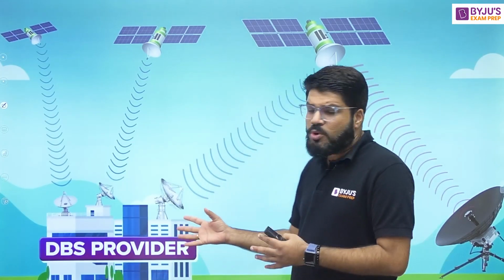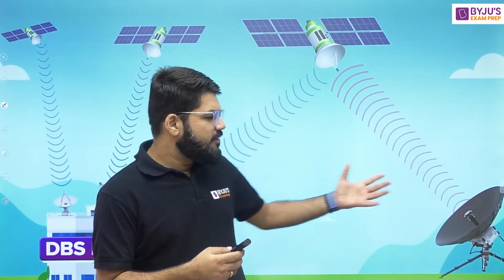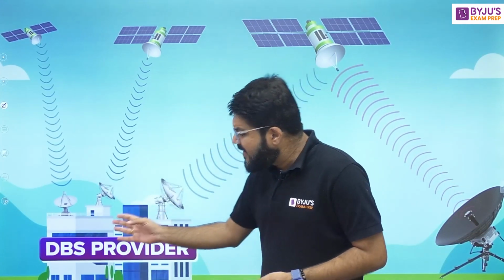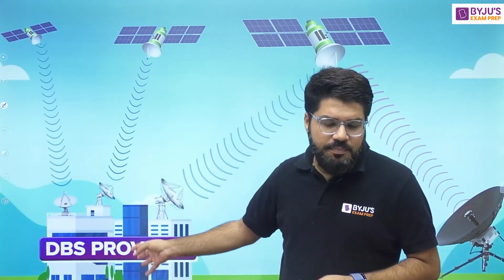Now that the DBS provider has collected the videos from the program source, that is the channel, the DBS provider already has its own broadcast center where they need to do video optimization, like MPEG compression. They need to standardize the bit rates, and they need to encrypt the video for privacy purposes. So after all this video optimization inside the broadcast center, the DBS provider will be ready to send the signal to its own transponder.